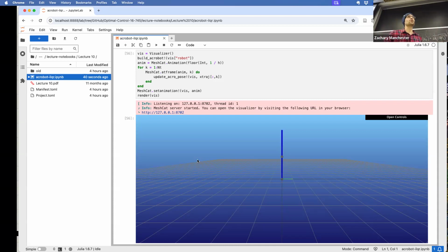It's cool. If you play with the cost, you can get different numbers of pumps. If you put a big cost on the R matrix, it'll swing up slower because it'll use less control effort, so it'll pump a few times. So you can get different numbers of pumps out of it. It's super fun. Next time.